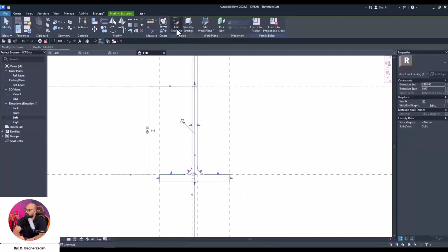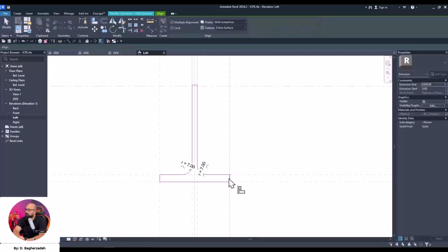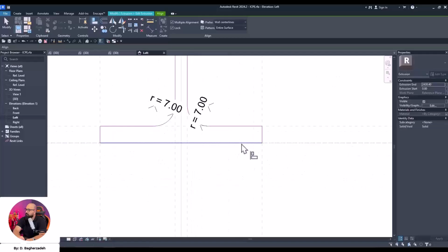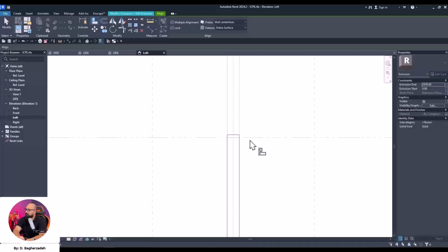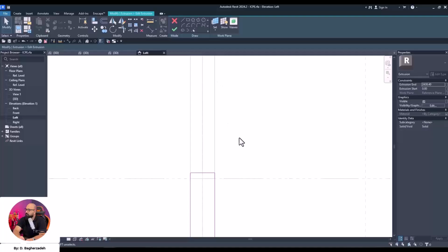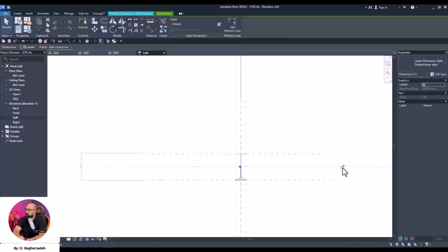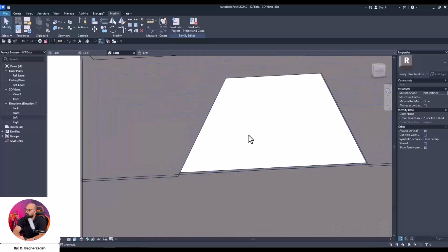So, select, edit extrusion. What's happening? All right. Now, again, we need to lock all the sections, all the parts of our section to these references. And yeah, all the parts, like the wings, the body, everywhere. Right, the radius is okay. Now, regarding this extra part up here, did I lock everything completely? Let me check. Yeah, seems fine, actually. Now, we can set a dimension for this extra part up here. Now, lock and finish.